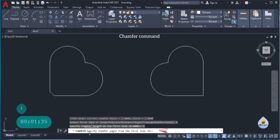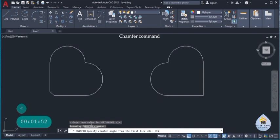Now it's telling me the angle that I want. I can set it to be 45 or 60. So let's say 45. I press shift, then the less than sign, then type in 45. Then I'll click enter.